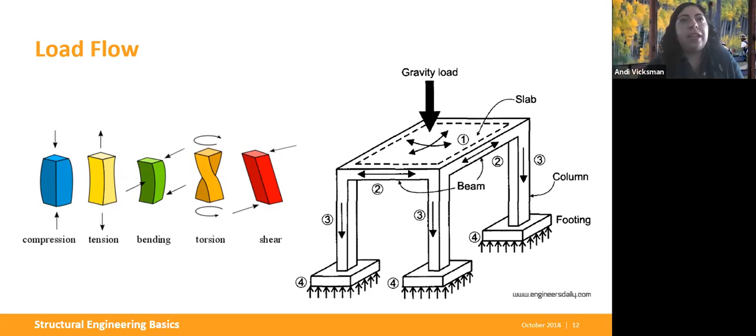Gravity loads. Enrique is talking about what we as structural engineers call lateral loads that act sideways on the building. So wind is definitely a really good example of a lateral load. Earthquake loads are also lateral loads because they shake the ground and cause buildings to have loads going sideways into them. So those are other great examples. What other natural elements could you think of that might cause load to a building besides wind and earthquake?